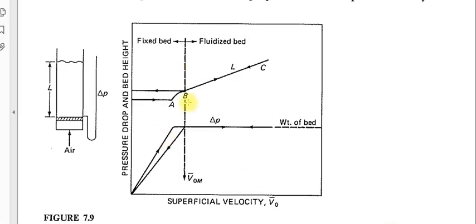So you understand fluidization. Fluidization is when the buoyancy force of the fluid acting in the upward direction overcomes the gravity force, and as a result the particles start to move in the upward direction.